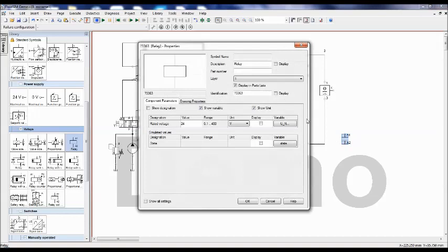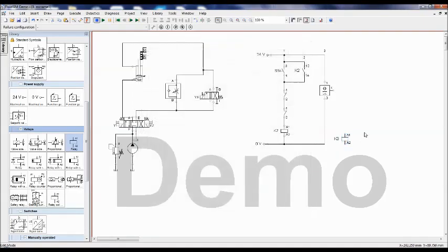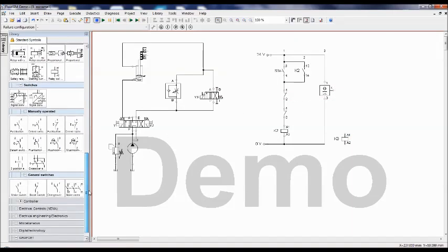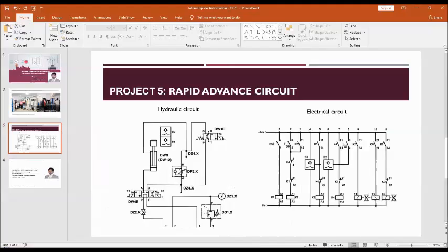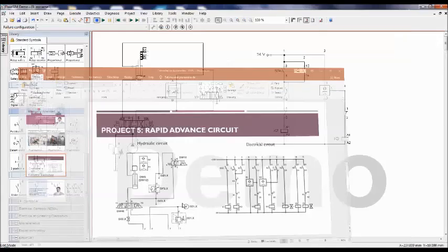K3 is given to the sensor not directly, because a normally closed contact is there, and then just link it to here. Okay, so here it is K4. K4 relay we have not taken, so I cannot link. So K3 should be there. That is a latching concept. So normally open contact.